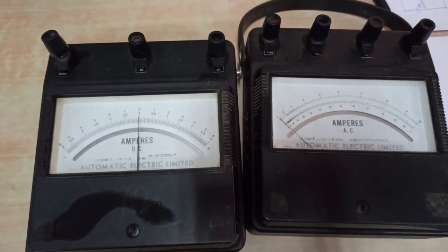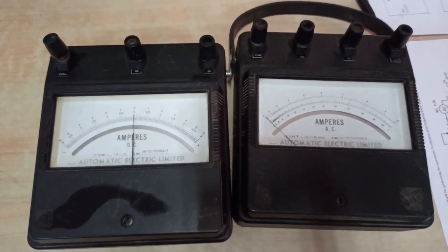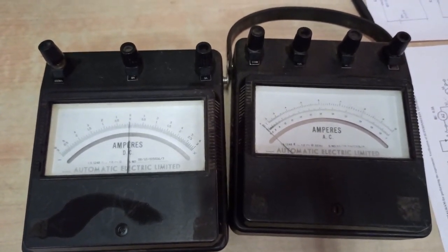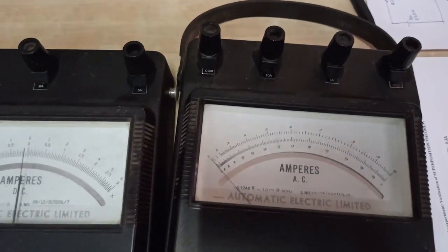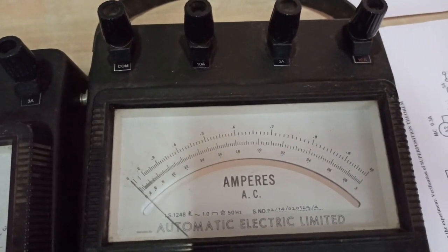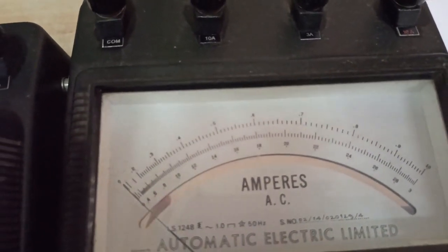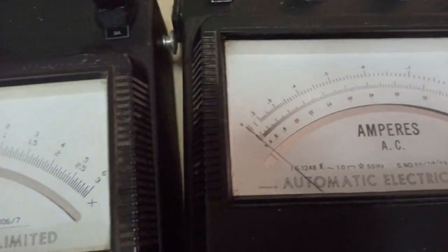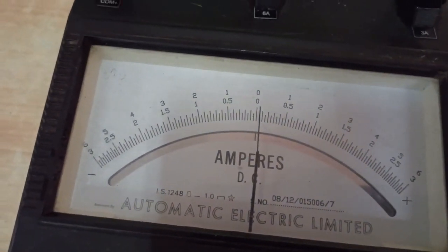As you can see on your screen, we have two different types of ammeter. One is known as MI, another is known as MC type. MI is moving iron and MC is moving coil. If you look at their scales, it will be quite clear. For the AC type of ammeter, which is MI, initially the scales are very dense, and in the later part they are quite uniform. And the scale of an MC type instrument is uniform.